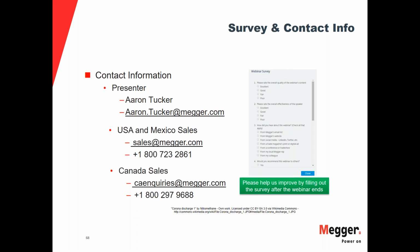Well, unless you have one of those special cases where your transformer has a voltage dependency for a TTR test. If you are using two instruments, where one was using 40 volts for the test and the other was using 200 volts, and you have a transformer with voltage dependencies, you will get different results. But otherwise, you could use any instrument, and any method, step up or step down, and you should get comparable results.